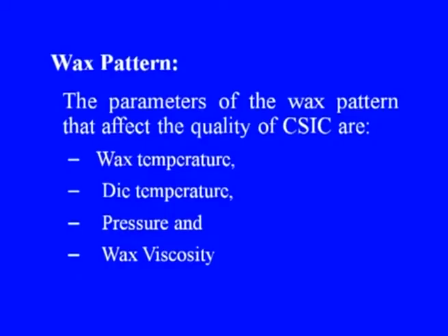This diagram depicts that the parameters are quality based parameters which affect dimensional accuracy, surface roughness, mechanical and metallurgical properties. The wax patterns. The parameters of the wax pattern that affect the quality of ceramic shell investment casting are wax temperature, die temperature, pressure and wax viscosity of course.